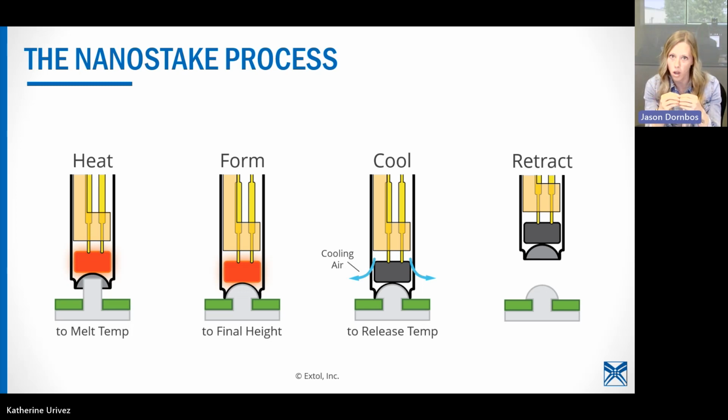Specifically, we see small bosses, used for tight little areas, and things that are maybe heat sensitive like PCBs. Anything along those lines is a good fit for nanoSTAKE. But the material, the actual bossed component, does have some limitations. If we're concerned about compatibility with the module, we will test the material. You can send your parts in. We'll stake it with a punch we have in-house, or you can purchase a custom module for your application and we'll assemble parts for you, just to get a feel for material compatibility with the module.